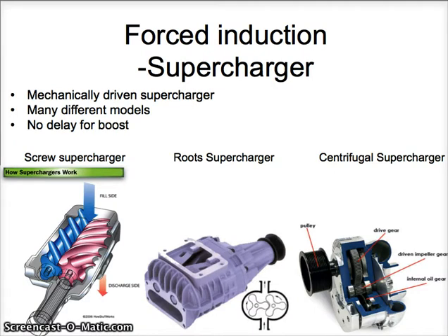Another type of forced induction is the supercharger. And the supercharger is a mechanically driven supercharger or compressor. There are many different models and there is no delay for the boost. It could either be of screw type, you could have the Roots type supercharger, or the centrifugal supercharger, which is more like a mechanically driven turbocharger. One of the drawbacks with a supercharger is that it takes some energy from the engine's crankshaft to rotate them.